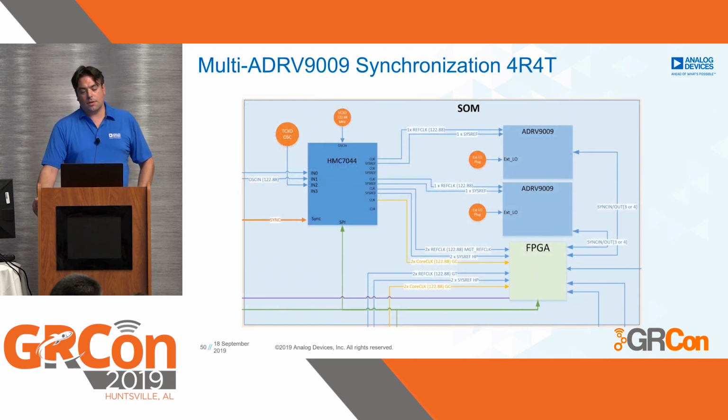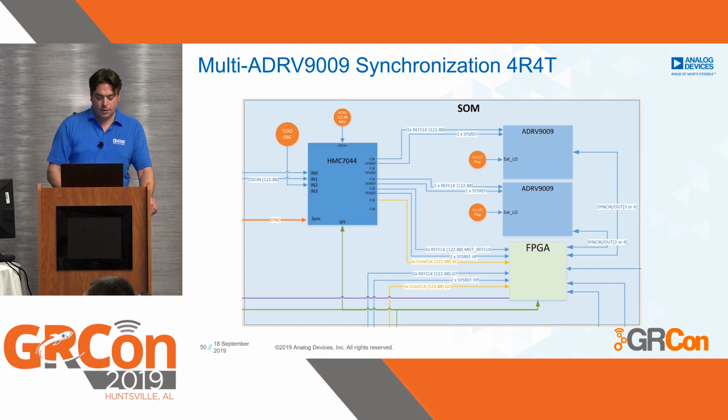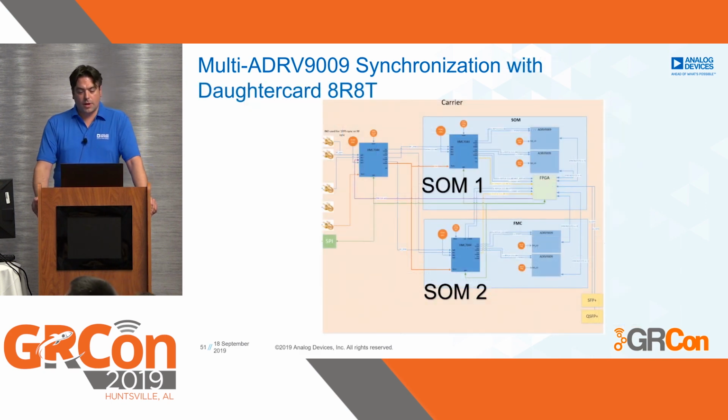This is how the setup is on a 4R4T on the SOM itself. So we have two ADRV9009s and one HMC7044, and it's just providing ref clock and sysref to both devices. There's nothing special in this setup. But of course, we see the sync input, which allows multiple of these system on modules to be synced.